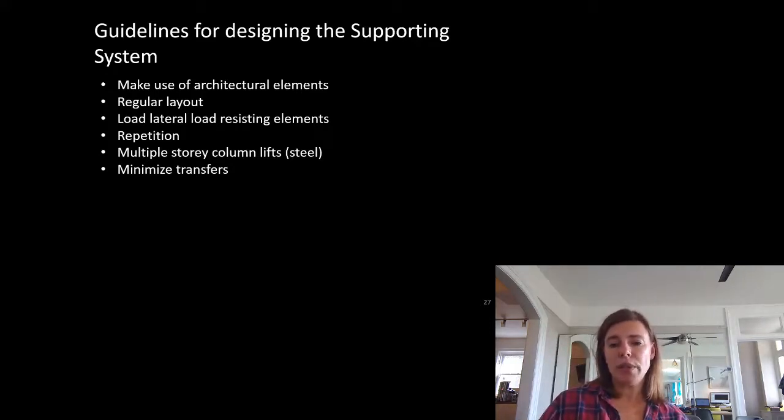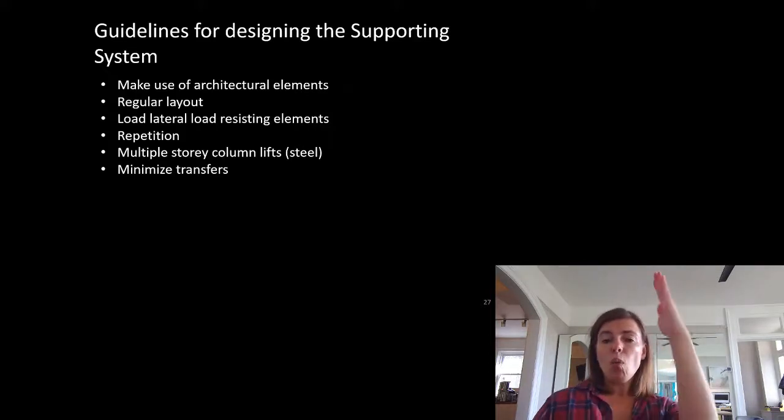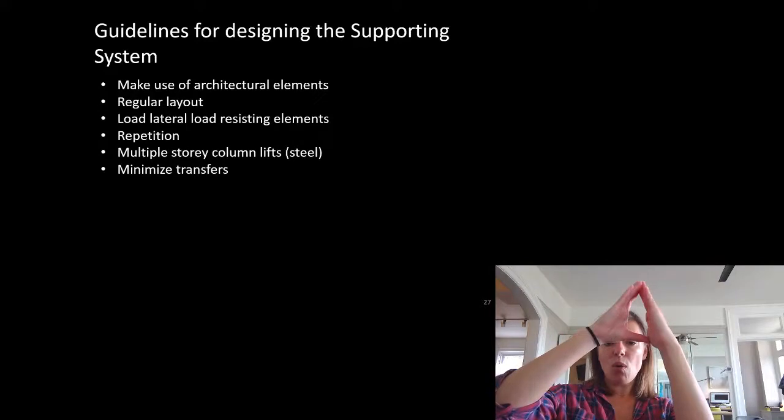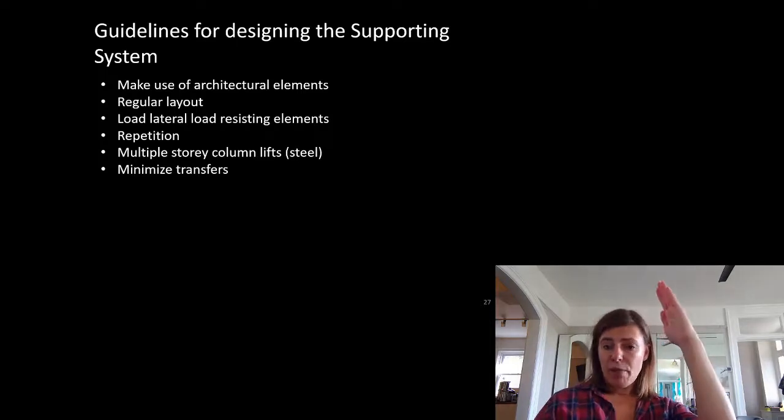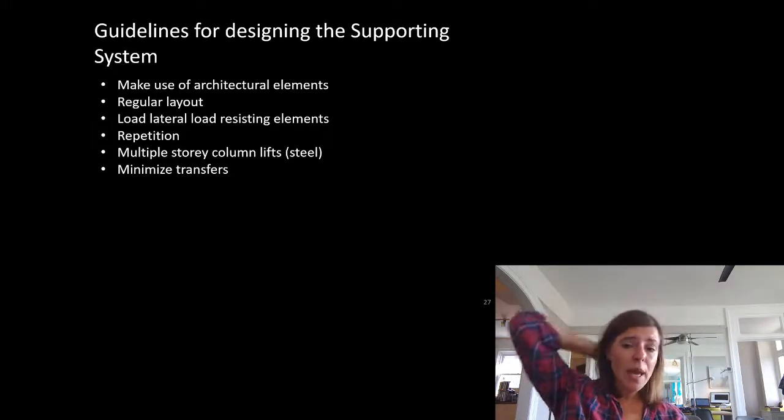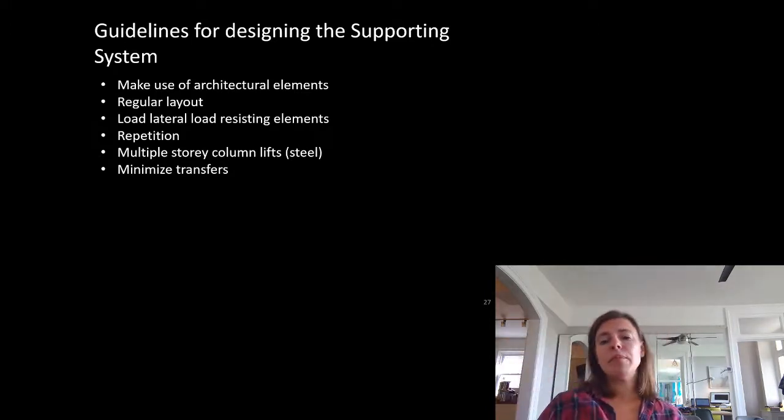On a 2-story building, you can probably assume that they're all going to come the same size. What happens though if this only has 50% of the load of this? Well, maybe it's worth making the change there. But if they're all relatively similar, it's cheapest to bring one element. If you get enough of a reduction in material due to changing it from floor to floor, that's when you might think about making that splice at a floor.